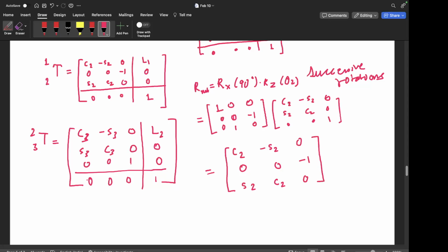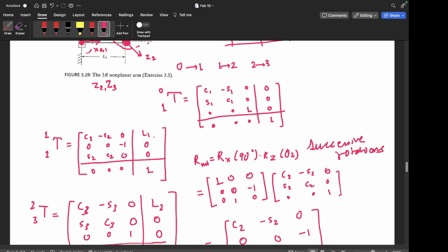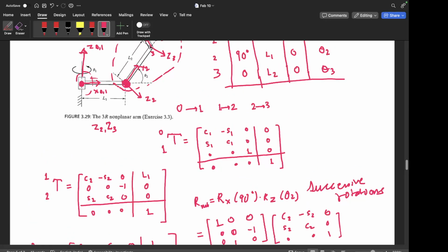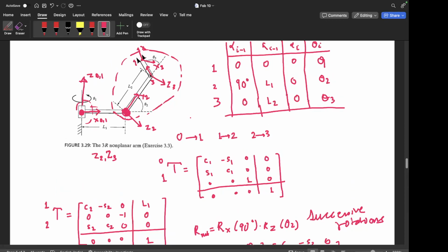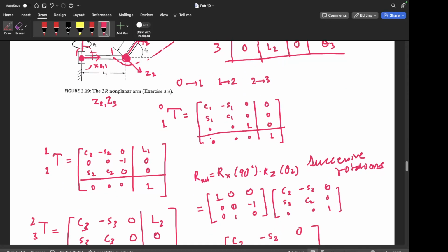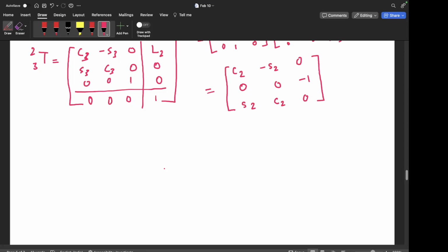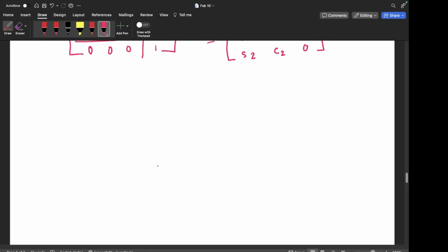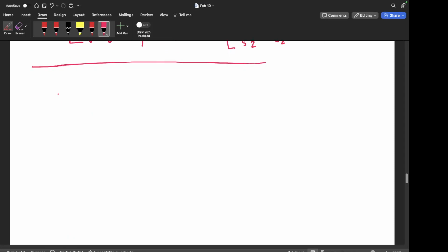Okay, so we have all three homogeneous transform matrices, and we wrote them without using any formula from memory. We just used the basic concepts of rotations and translations. For simple systems, I would suggest you write like this, because this will help you much more than just remembering a formula and putting values in it.